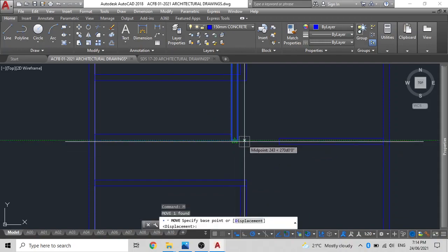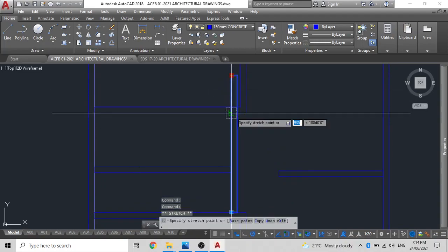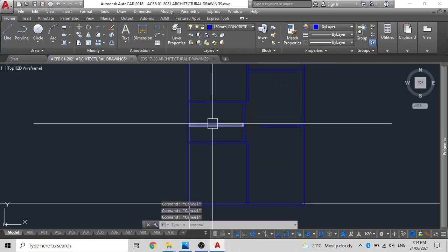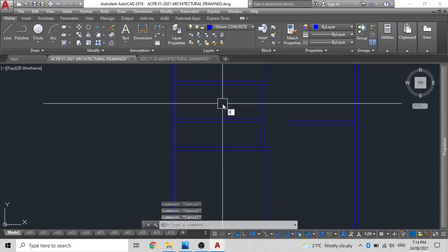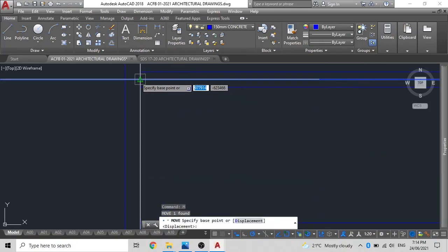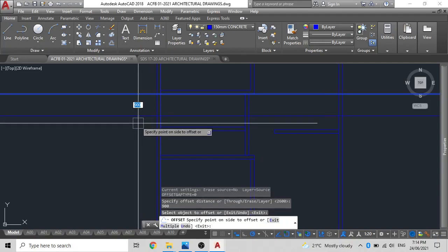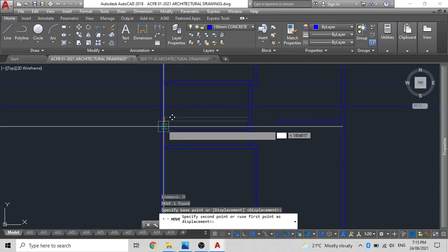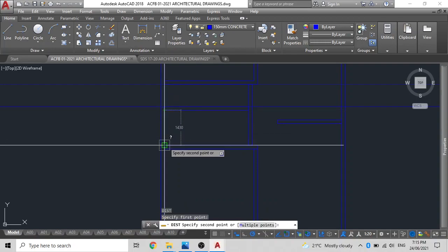Now you don't really have to worry about this being perfect, but if you wish it to be perfect, you can make it. The design will work for you. So what we can do is we can place this section as our shower and this section as the washroom. So the washroom will be 900 millimeters in width. That is more than enough space for a standard simple washroom. And our wall will be outside of the 900 mm mark, like so. And the remainder of the distances will be the shower, which is 1430.